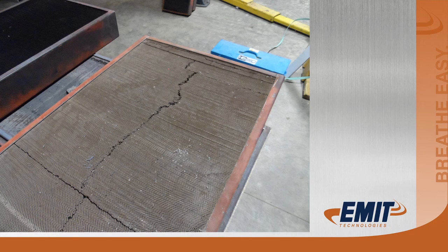The exhaust temperatures were actually about 250 degrees hotter than what their panel was showing, and therefore it was not going down on shutdowns. And the engine was running rich as well. It's kind of a common practice on Waukeshas to run a little richer than most engines. So this is what extended periods of high heat do.